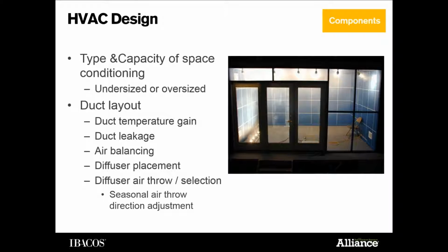And then the last two, sorry: diffuser placement, and diffuser air throw and selection, are critical, because the volume of air we're pushing through this house in a low-load home is probably half the amount of air that we've typically pushed. Actually picking that diffuser and making sure that it can throw air with a certain velocity is going to become critical.